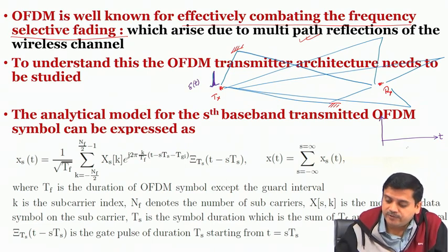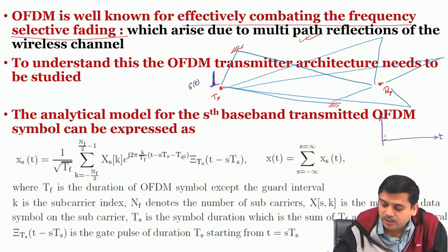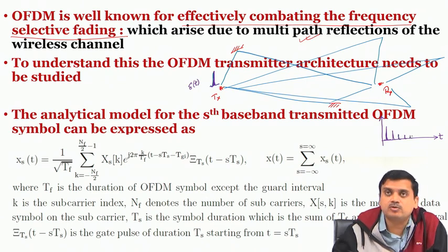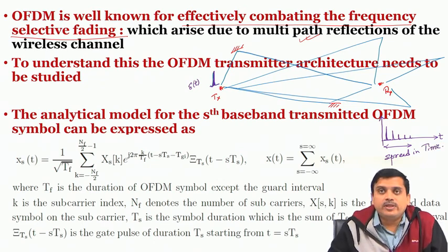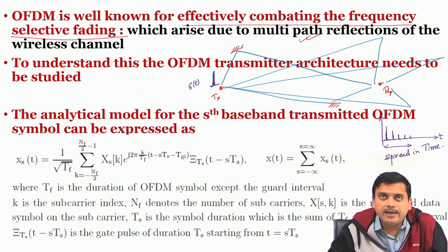the first path, we have discussed this thing, but we are doing it in short, is kind of arriving after a certain propagation delay corresponding to the delay of the first path, then of the second path, third path, fourth path, and so on and so forth. So, effectively the impulse gets spread in time, right. So, when things get spread in time, things in the frequency domain would get restricted or shortened.